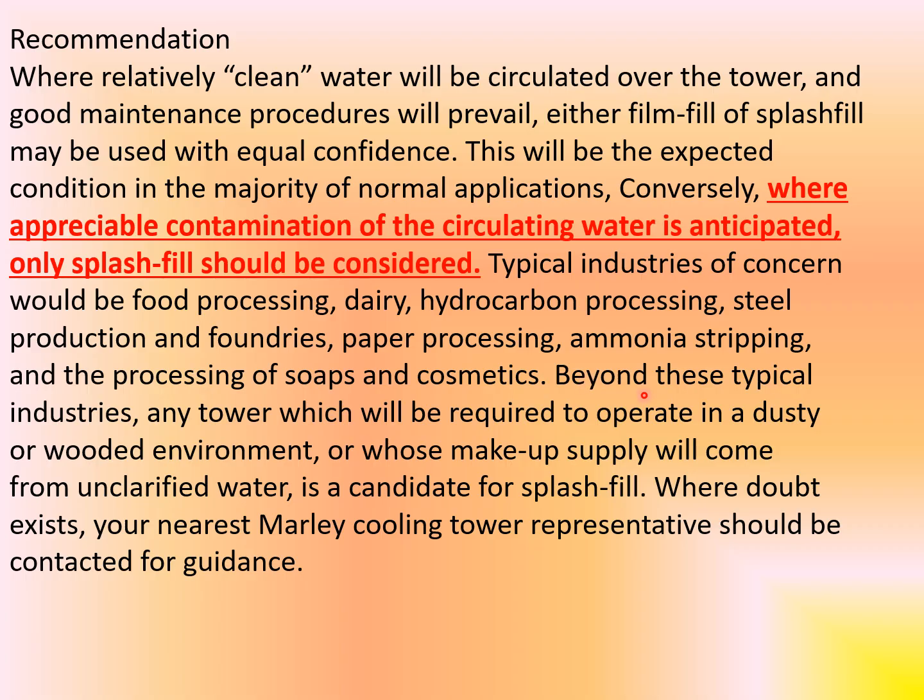Beyond these typical industries, any tower which will be required to operate in a dusty or wooded environment or whose makeup supply will come from unclarified water is a candidate for splash fill. Where doubt exists, your nearest Marley cooling tower or another manufacturer representative should be contacted for guidance.